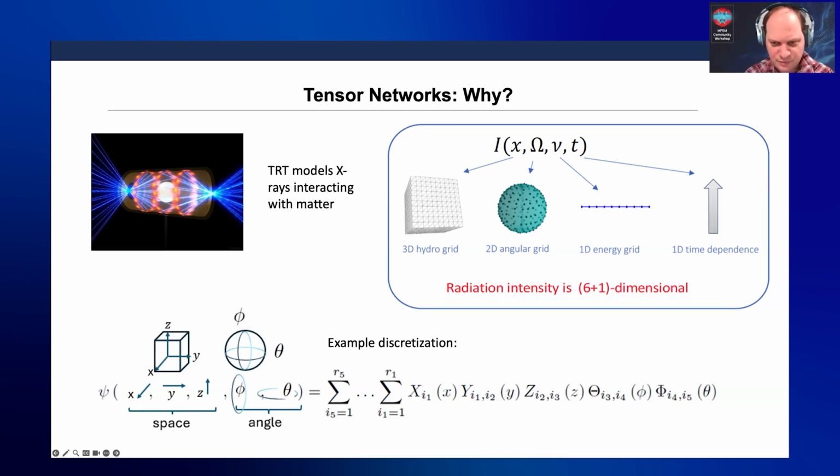To get it right, part of the story is these thermal radiative transfer models. These are really complicated and difficult because at every point on your 3D grid, you're going to have an angular discretization, a unit sphere discretization pointing out in every direction.